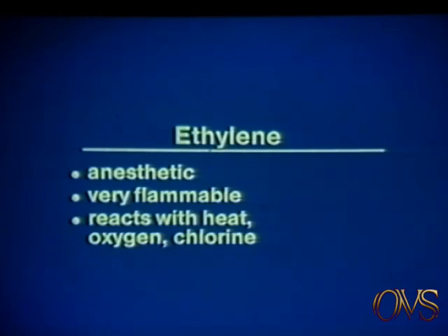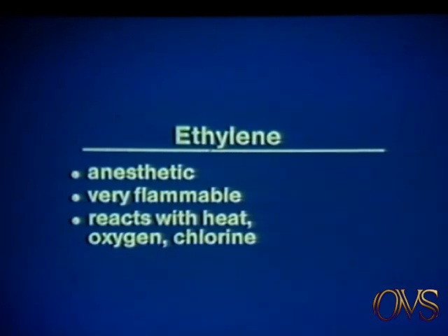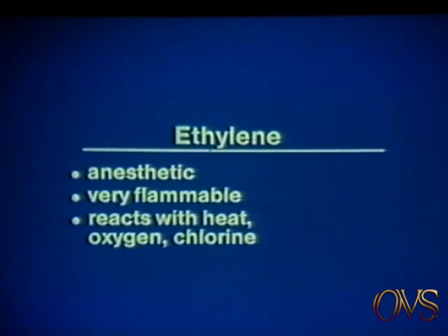Personal protection requirements when you make contact with ethylene include SCBA in high vapor concentrations. Ethylene gas is not harmful to skin. Safety glasses should be worn to avoid a jet of gas, but chemical goggles are not required. Unlike other gases which are liquefied, ethylene is transported under pressures which allow it to remain a gas, so the freezing effects of liquefied gases are not a hazard.